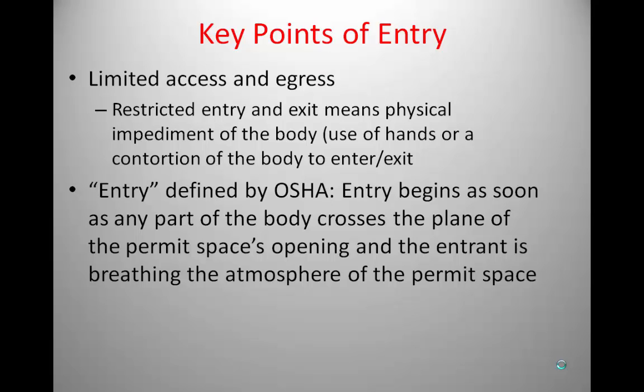Key points of entry, limited access and egress, we talked about earlier as one of the definitions of a confined space. One thing to keep in mind as well, OSHA defines an entry as soon as any part of the body crosses the plane of the opening and that entrant is breathing the atmosphere of that permit space.